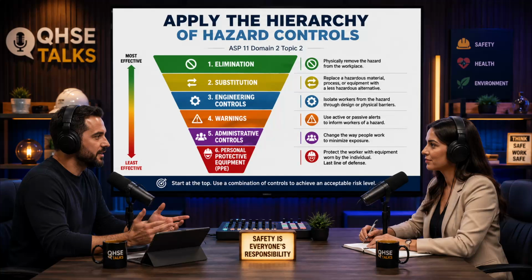Walk me through it. A worker must recognize the need for maintenance, formally shut down the machine, identify all energy isolation points, physically apply the locks and tags, and most importantly, attempt to turn the machine on to verify a zero energy state. Right. Every single one of those steps requires active human cognition and compliance. If a worker is rushing because the production line is down and costing the company thousands of dollars a minute, they might skip that verification step.